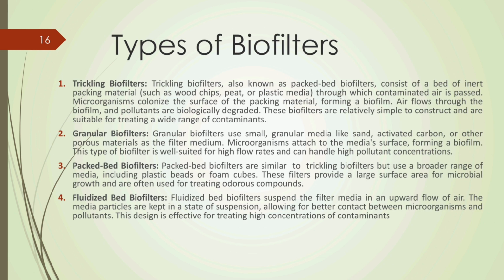Types of biofilters. First is trickling biofilter. Trickling biofilter, also known as packed bed biofilter, consists of a bed of inert packing material such as wood chips, peat or plastic media, through which contaminated air is passed. Microorganisms colonize the surface of the packing material, forming a biofilm. Air flows through the biofilm and pollutants are biologically degraded. These biofilters are relatively simple to construct and are suitable for treating a wide range of contaminants.